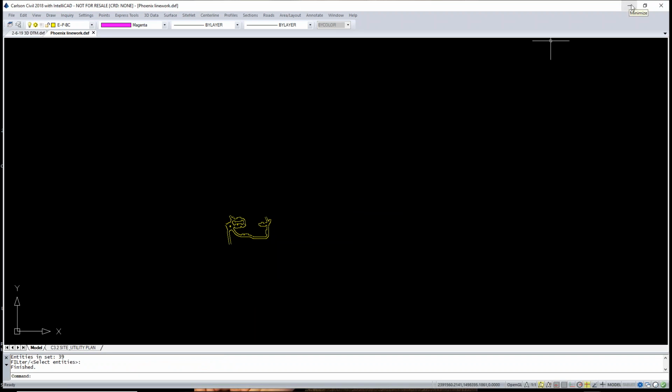So for the newer stuff, DXF elevated, XML, and the PLN for the alignment. Older stuff, flattened DXF, TIN file for the surface, and still the same PLN.